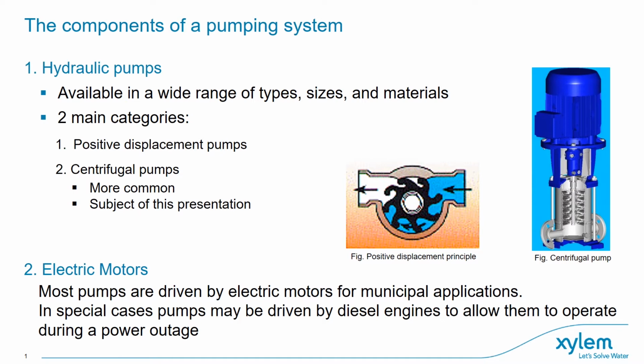Positive displacement pumps make a fluid move, trapping a fixed amount or volume at the suction and forcing it mechanically into the discharge pipe. Pumping action is cyclic and is mainly driven by pistons, gears, vanes, or other means, depending from the single application. This typology of pumps is characterized by a fixed displacement volume, while centrifugal pumps add kinetic energy using a spinning impeller. As the fluid flows, the kinetic energy is converted into pressure.